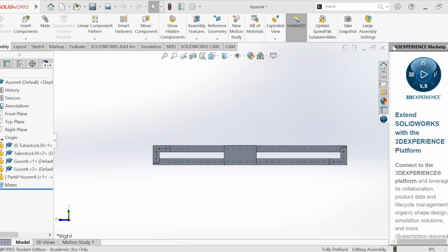Great. So now that we've created all of our parts, and we've created this new part specifically in the context of this assembly, let's think about how we were going to save this part. We have two options. SolidWorks provides us two. Only one of them is really a viable option for the way we work on this team. The first option is to save within the context of this assembly. So what that does is it just saves this file into the file of the assembly rather than as a separate part file. We do not want that just because of how we organize our files. We'll go over that later.